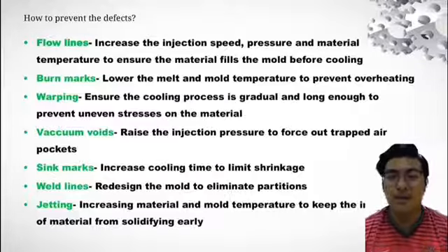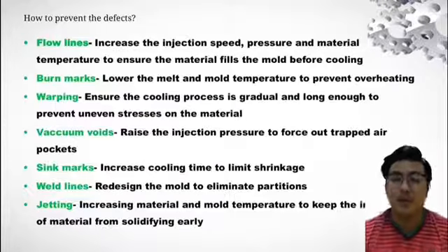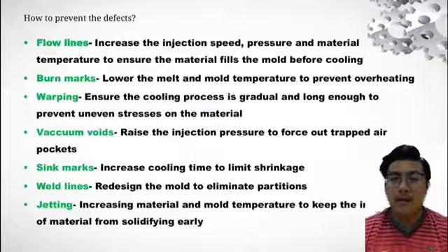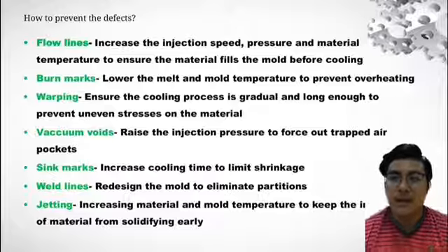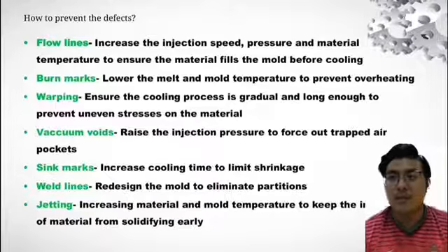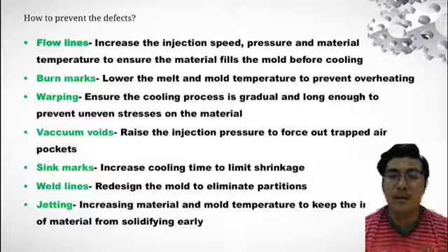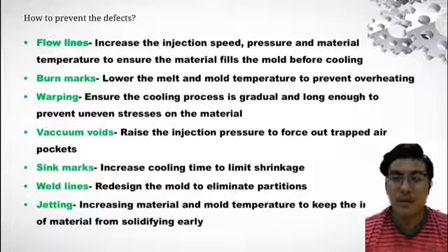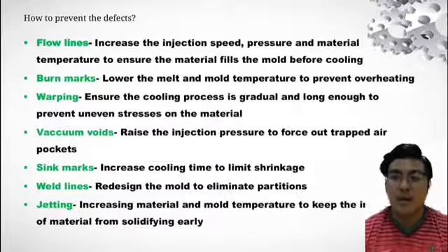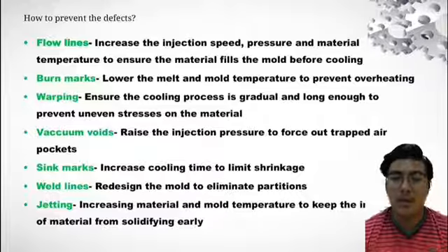I will discuss how to prevent the defects. First, flow lines: increase the injection speed, pressure and material temperature to ensure the material fills the mold before cooling. Burn marks: lower the melt and mold temperature to prevent overheating. Warping: ensure the cooling process is gradual and long enough to prevent uneven stresses on the material. Vacuum voids: raise the injection pressure to force out trapped air pockets.